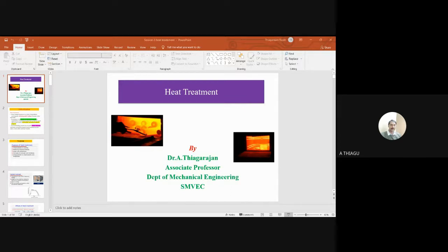So this is a furnace where the sample is positioned. This is a steel sample. The sample should be allowed to heat for 40 to 100 hours at a temperature of 500 degrees. Here the ammonia gas will be involved. Most of the nitrogen will be deposited on the outer surface of the material, right? The hydrogen will be exhausted or collected from the gas outlet.